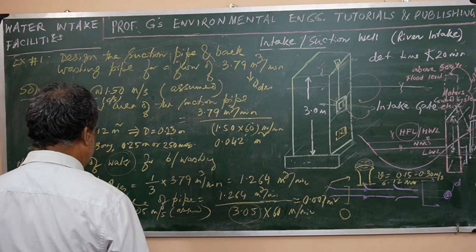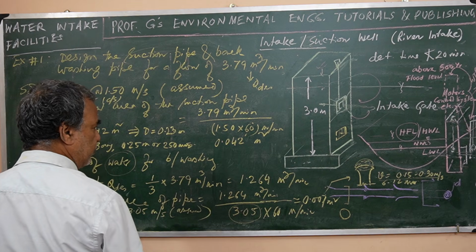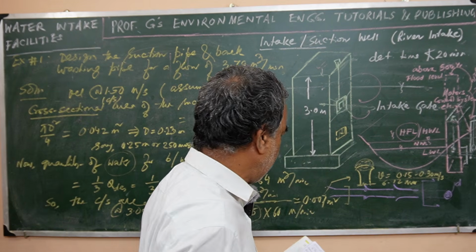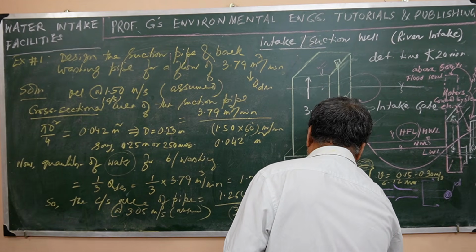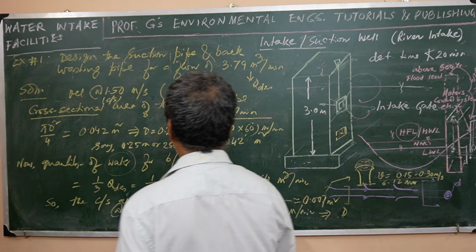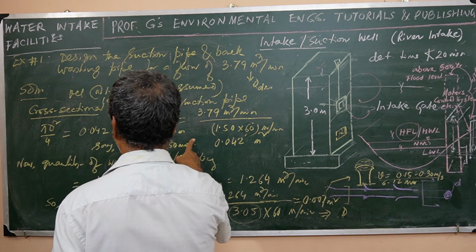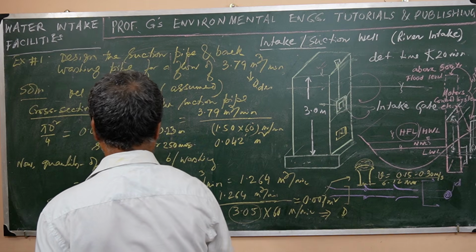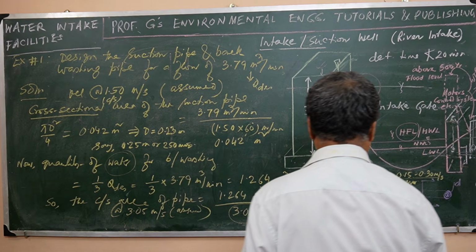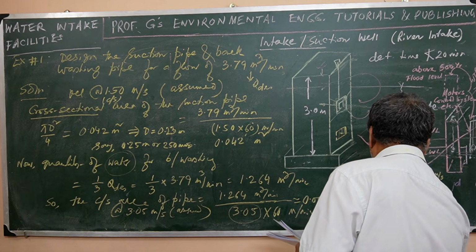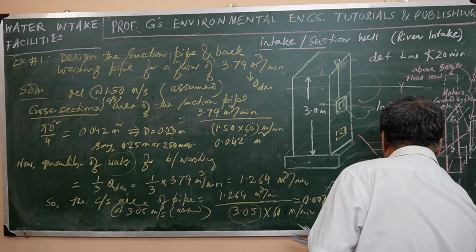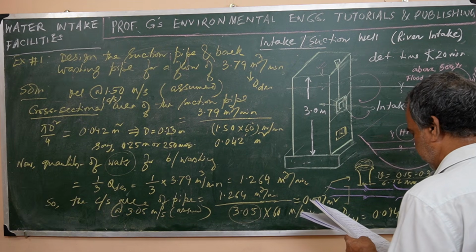And the diameter, same principle, using the same formula also. This will require a diameter from pi d square by 4 again. So this is the d for, maybe the suction pipe you can write, backwashing d bw, and for that time the s you can write, suction. So this will be 0.094 meter, say, to round it off and to select the next higher size also.